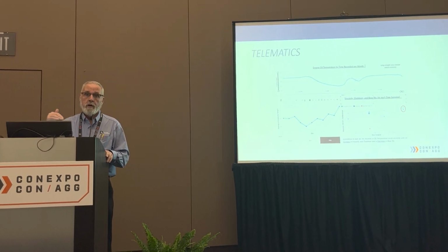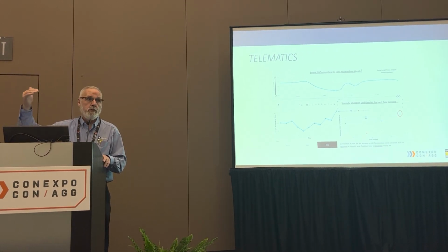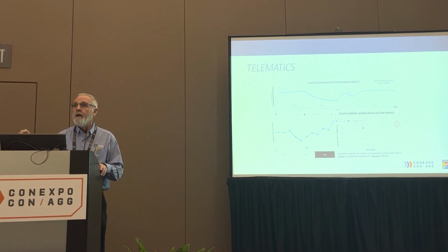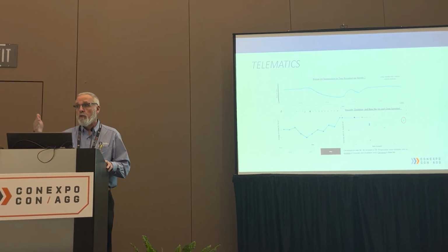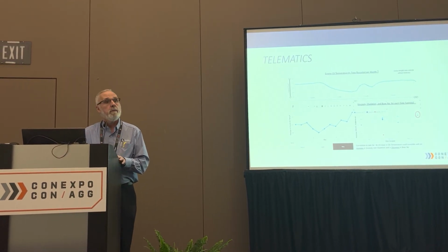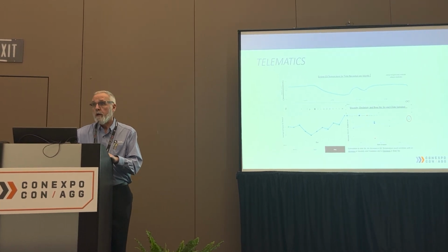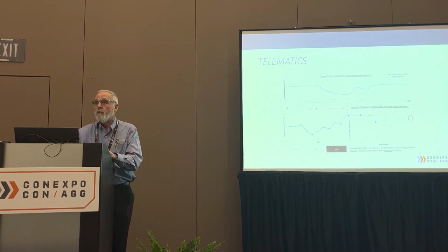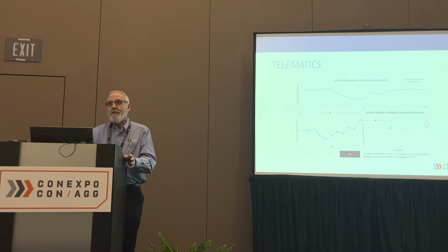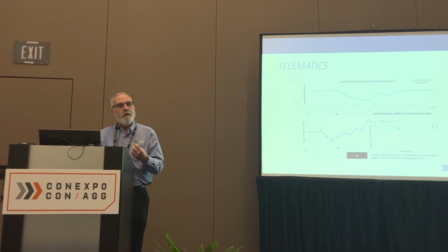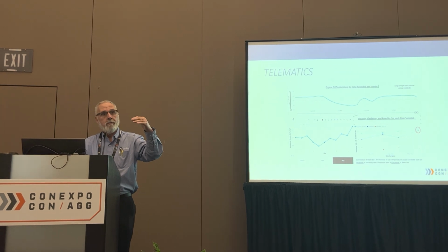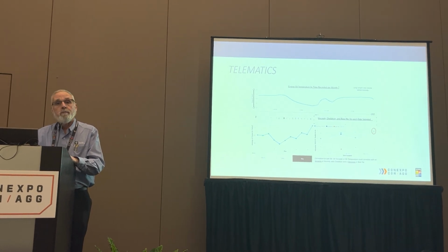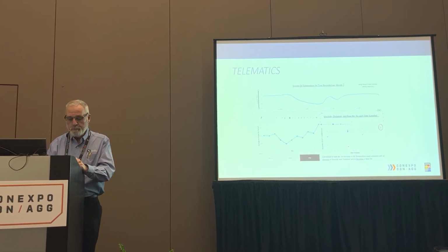In instances where the telematics showed the operating condition was up to 260, 270, you could develop a direct correlation of, now you've got to be down at 250 hours when so many occurrences of this exist. And really useful for the customer, right? Because you don't want to just take it blindly, but yes, we can extend out to 500 hours and be good. The last thing you want is to realize the value of increasing your drain intervals, but you sure don't want to do it at the risk of component health. So a lot of things go into consideration here.